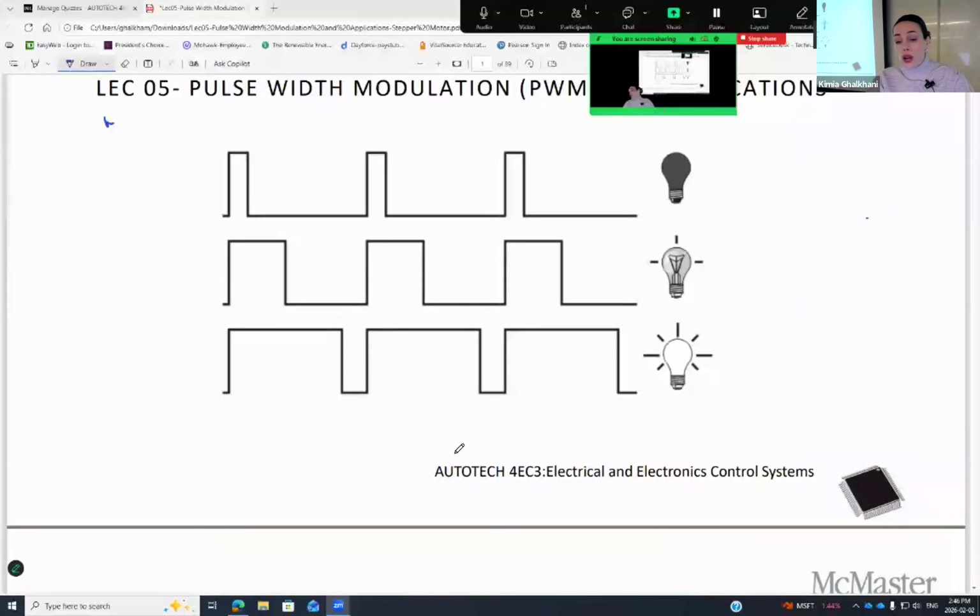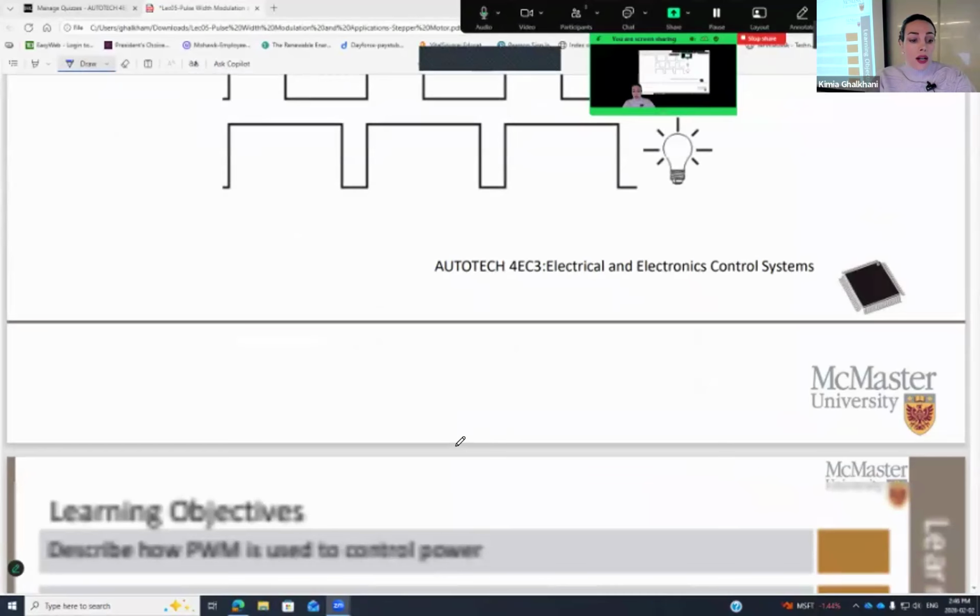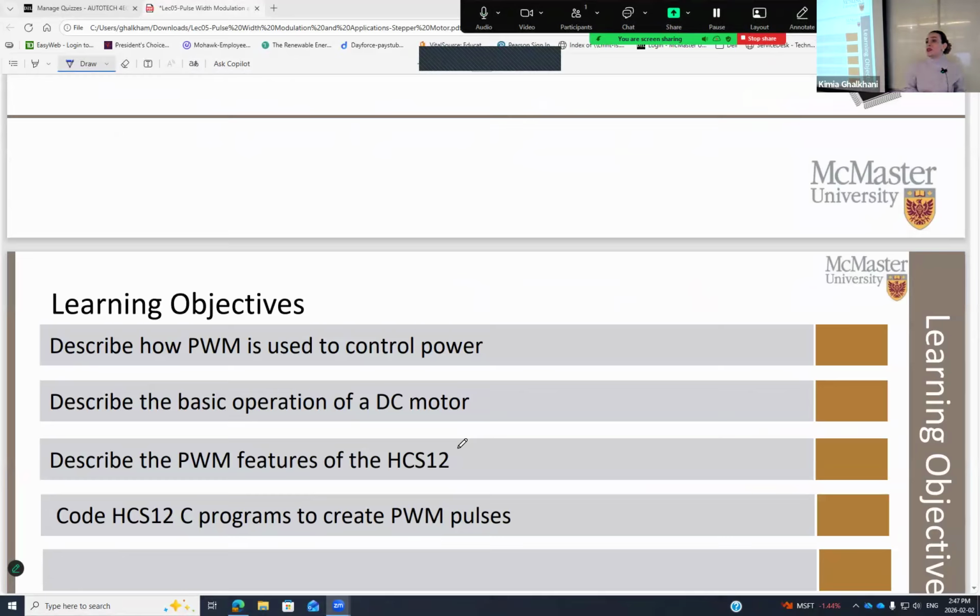Again, does a DC motor have an analog signal or digital signal as an input? Which one is it? Who can tell? Analog or which one? You are going to look at your DC motor. What do you have through your DC motor? We are going to control the speed. We are going to control the direction of rotation. How are we going to do that? Through analog, right? But we are going to do it through another, different method, and that's called pulse width modulation.